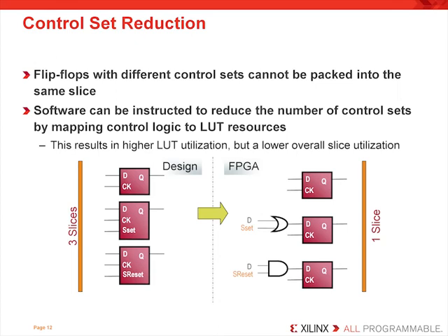Xilinx recommends designers build with as few control signals as possible because it usually affects the device packing. This, as I mentioned earlier, is because the designers don't understand their device's register resources well enough. So on this slide, we are showing flip-flops with different signal needs. Since these flip-flops don't need the same combination of control signals, they cannot be placed in the same slices for maximum efficiency.